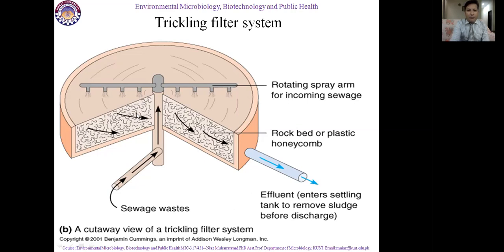And this area is made up of pipes at the bottom to collect the fresh water, and it is supported, and further sand has been added over here up to 3 feet. On the surface of the sand we spray the sewage water. This is a sand bed, and the bottom is covered with pipes and gravels, which have further been filled on the upper side with sand, and we are spraying this sewage water on the sand.